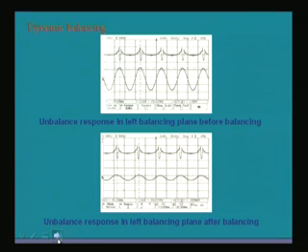This is another signal, especially one which is used in the balancing of machines. You can see that this particular signal is the vibration signal of a shaft. This is the reference signal which I showed earlier, that is used to measure the phase of this particular signal.